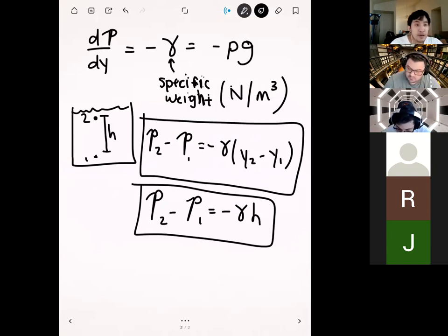And so the key to these hydrostatic problems is that the only thing that matters is the height, right? I think we ended last time saying if you travel in a horizontal plane, you're always going to experience the same pressure because you're always going to be at the same height. And in particular, when you're looking at containers of fluid, it doesn't matter what the container actually looks like. As long as the height difference is the same, then the pressure difference is the same.